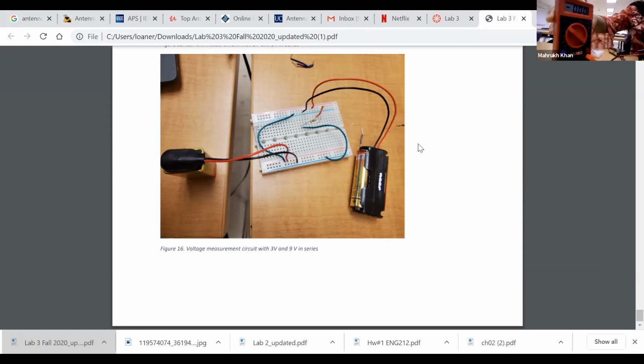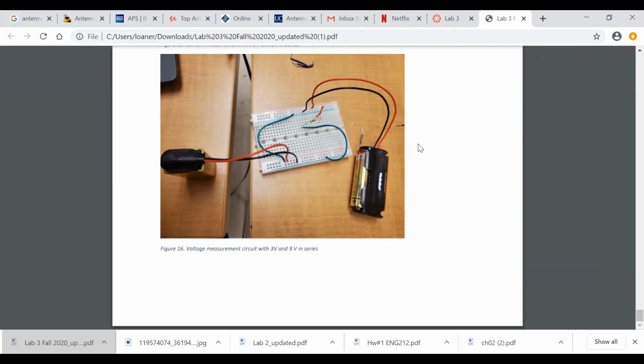And then I am showing you the voltage I'm getting across the resistor. So it's like 11.7, right? Yeah, that was the highest. And if I just swap my leads, I'll get negative voltage. So it means that it's fine. So it's 11.7. This is a 12 volt battery together, 3 volts and 9 volts, okay? Then I will take my batteries out and check your circuits, okay?